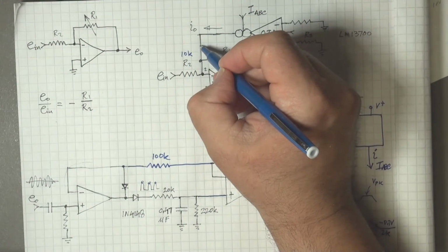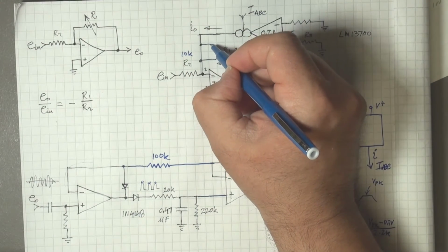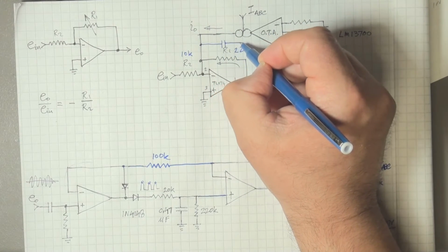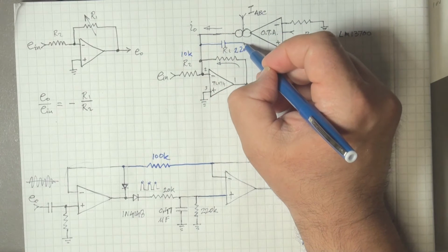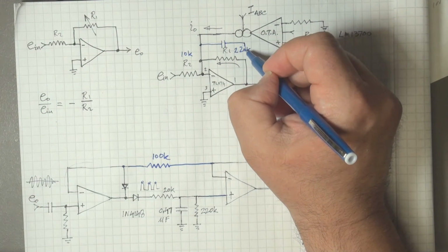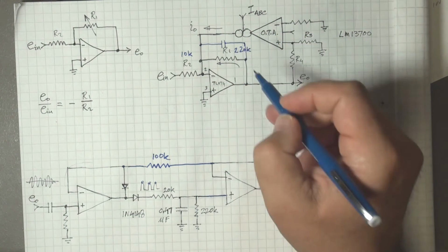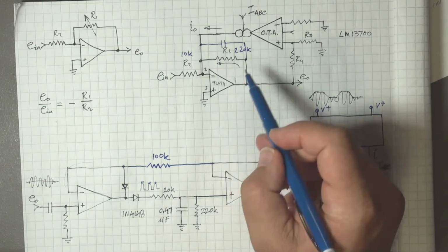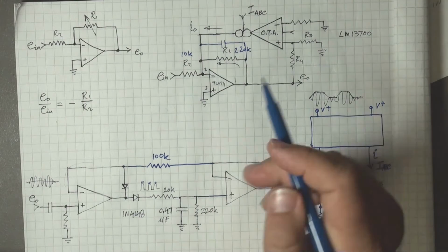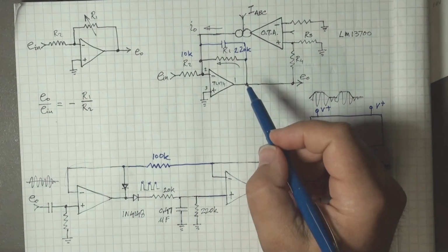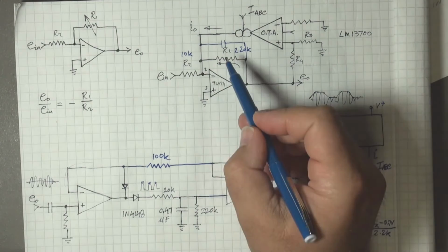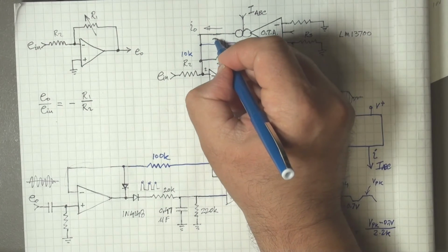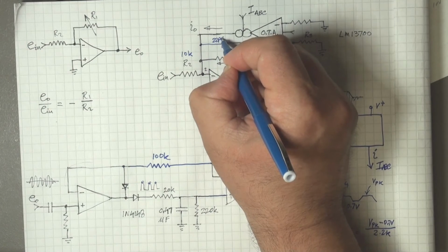And in addition, it's optional, but you might need a small capacitor, maybe 18 picofarads or something, to prevent this from self-oscillating. I didn't have this problem, but in any practical implementation of the circuit, this capacitor will definitely be there. Maybe 18 to 22 picofarads.